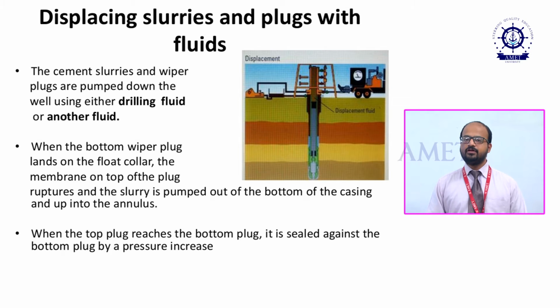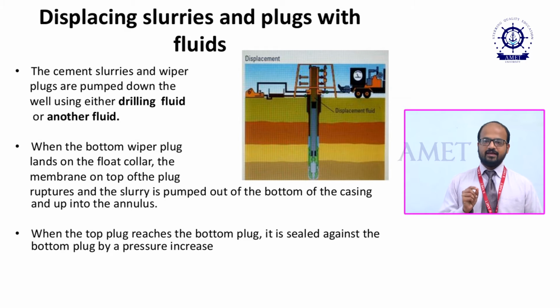With a solid, how will the cement go to the bottom, because there won't be any communication or any hole? Now there will be one diaphragm, which exists in the bottom hole. I have to give more and more pressure, because I have to pump with the help of cement slurry followed by the spacer fluids or some other displacing fluids.